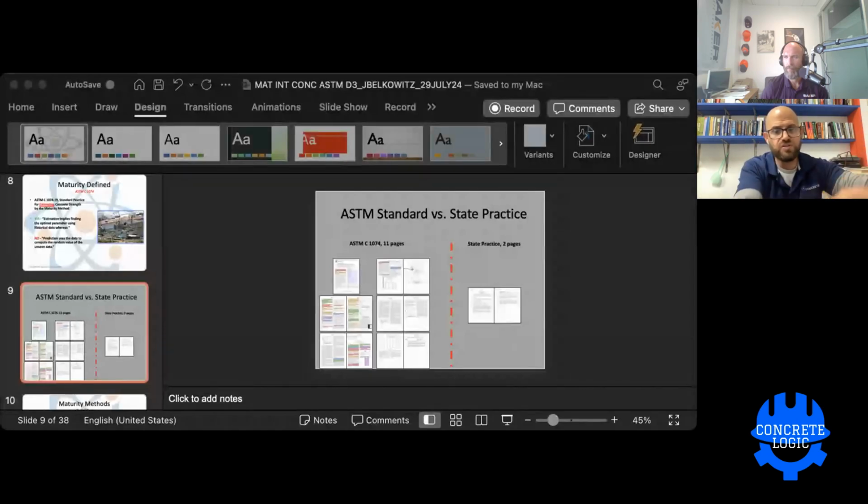Yeah, hold on. We were having a lag over here, so I kind of half heard your question. Can you ask it again? So let me read that. To account for the reduction in long-term concrete strength due to high early age curing temperatures, the test specifier could require that specimens be moist cured at an elevated temperature close to the expected average in place temperature during the first 24 hours after placement. So are they saying, yeah, so instead of curing at whatever 75 degrees in a bath at the lab, my understanding is they should increase the temperature to what it could possibly be at the in-place concrete. Is that right? Yes. And I get into that here in a little bit.